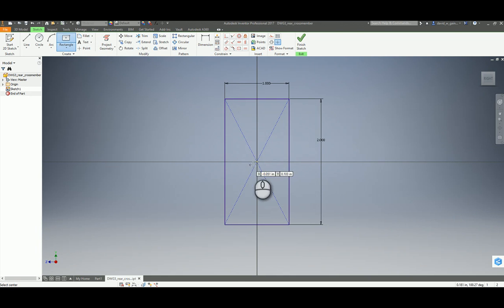Left click again on the rectangle, come to the center, and move up. Now you'll notice as I move, it will jump onto the line. That means that corner is constrained, but we can't make the right geometry. So it's a good idea when you're creating this to make sure that the point doesn't auto constrain to another